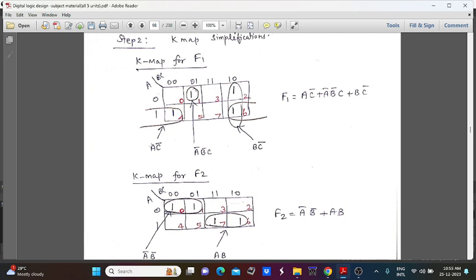So wherever the output is 1 in the table for F1, at that place we just put a 1. The remaining minterms are assigned as a 0. Here I put an empty column because whenever I explain, I just leave it empty, and after the explanation, I include this 0 for the remaining columns. So here the 1s are taken, and we have to map them.